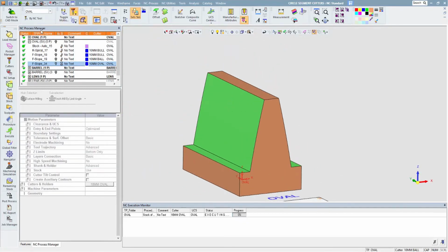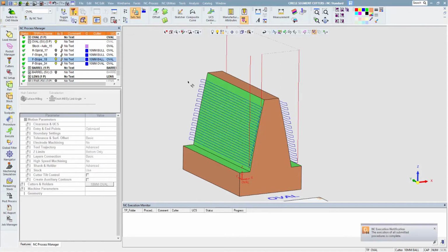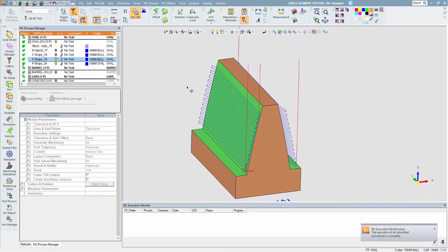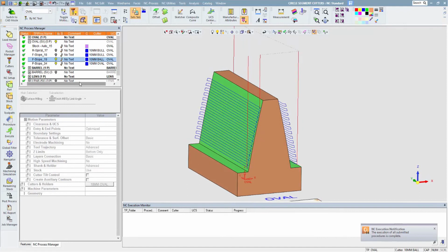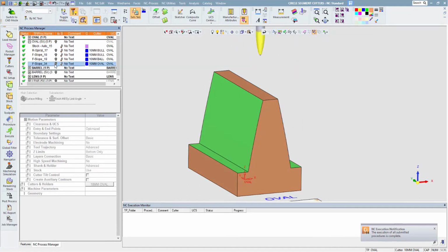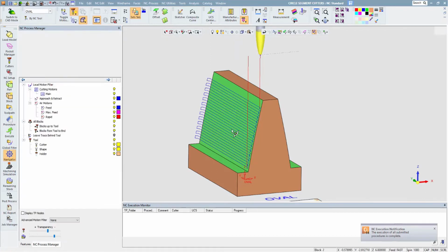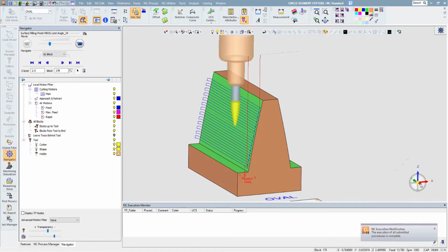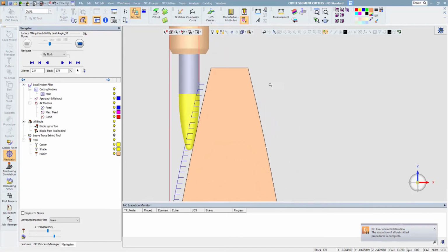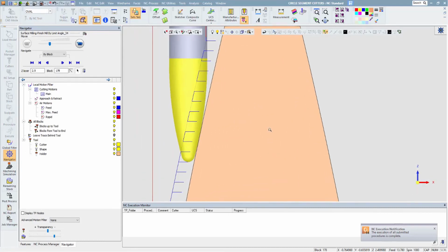Now the toolpath will look very similar from side to side. You can see we have a different start, but they're very similar when we look at them. So that is to show with the same step what we're going to get with that. Now, when we place this tool and we look at this from the side, look at the cutter engagement difference. So even in 3-axis, in the right application, we can see a dramatic increase in the surface contact of that tool when it's used correctly.